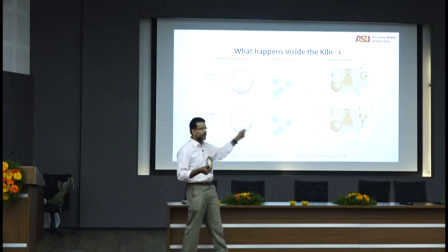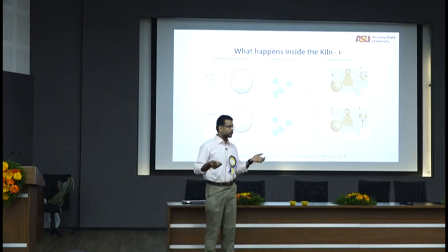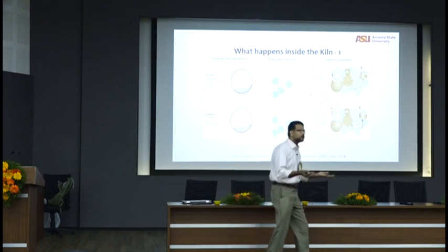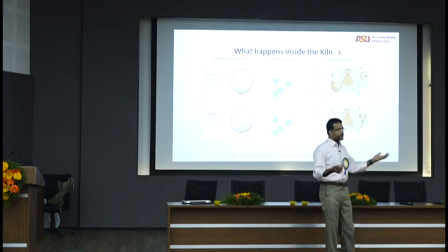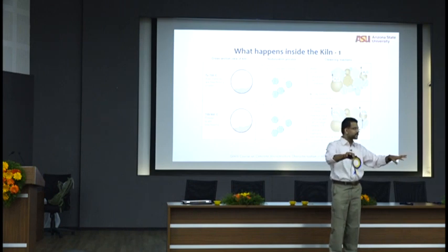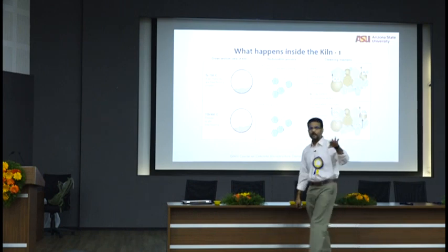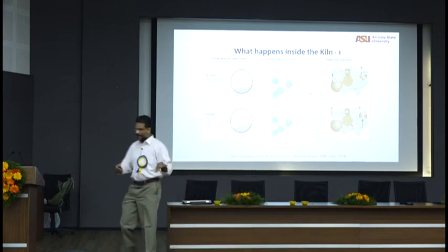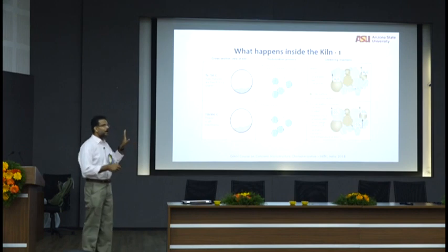Now, because you have calcination happening, if you're a process guy interested in cement manufacturing and want to know where my temperature should come from, calcination is an exothermic reaction. Because your CaCO3 is becoming CaO and CO2, you have heat also being generated. Therefore, the process doesn't have to give external heat at that point. Your 850 degrees Celsius is roughly maintained in the kiln because of the exothermic reaction of calcination. Okay? So that is your first idea of what happens in the kiln. And basically what I have told you is when C2S forms. Okay?